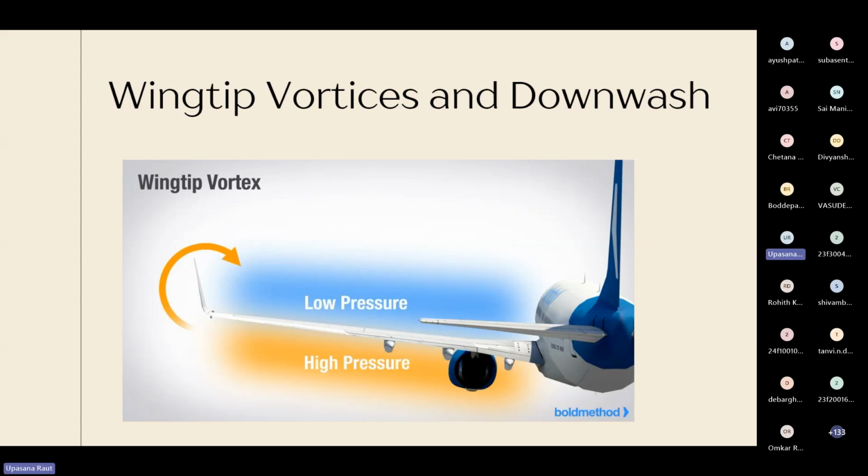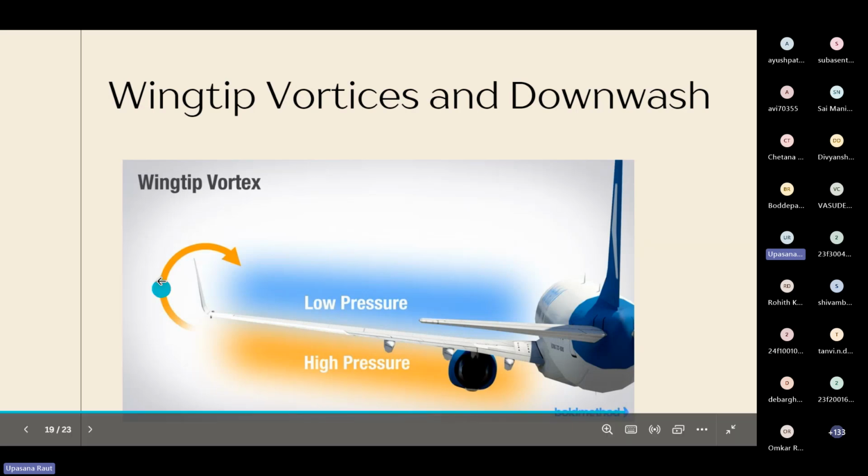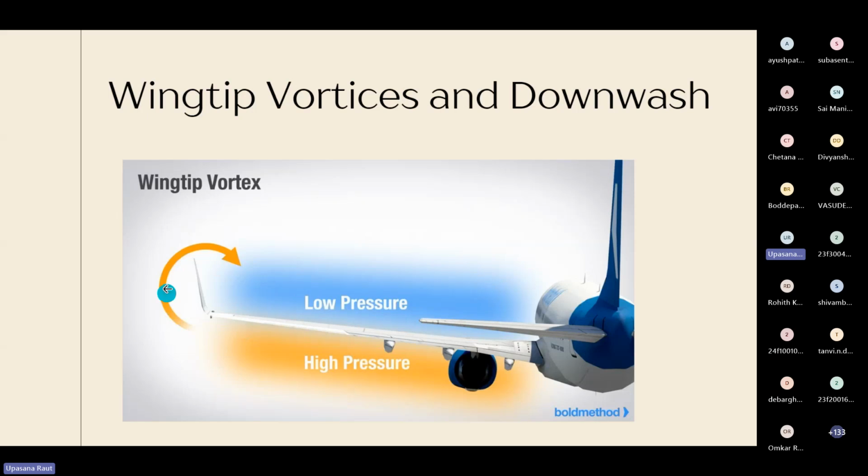So they will basically leak out around the edge of the wing. At the tip of the wings, they leak out in a curled manner. There would be curls formed around the wing. These curls are called wingtip vortices. You can think of it as a trail of spirals emerging from the tip of the wing.